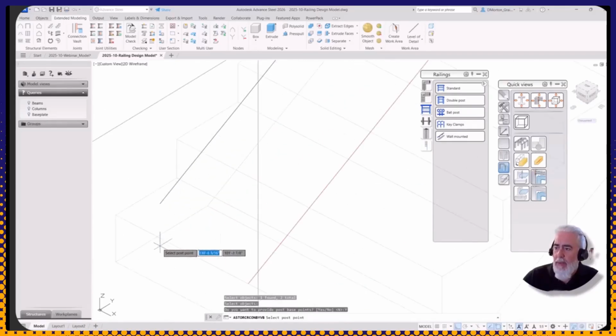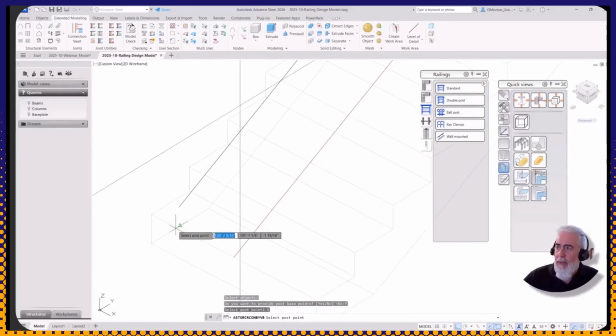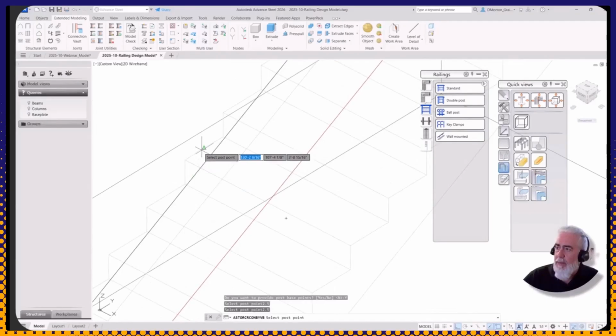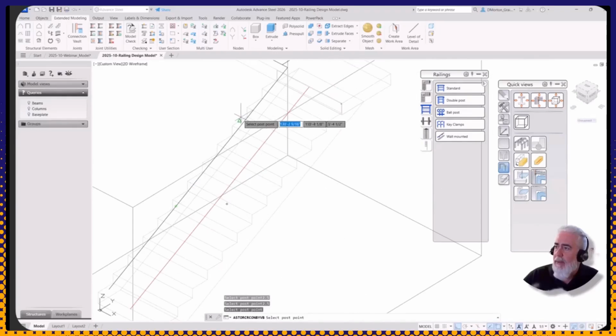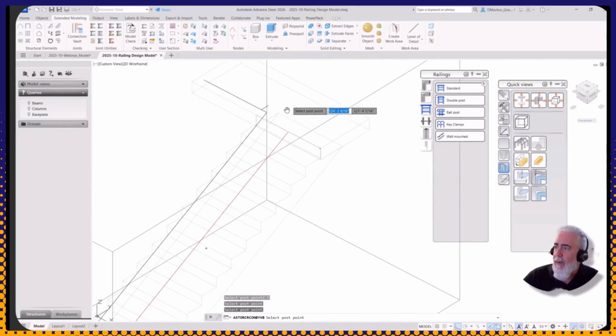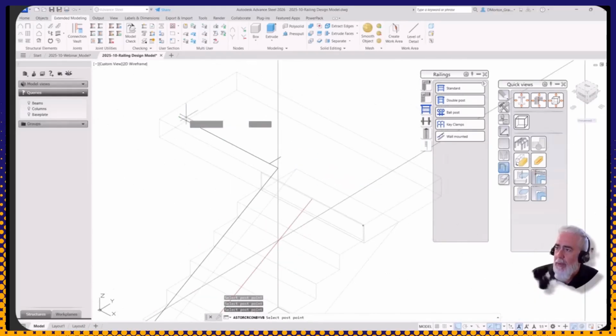And then I want to provide the post base points so they come out where I want them to show up. So here, I'm just going to come from the edge and I'll come in 2.5 inches. And I'll go up 3 stairs. I'll do the same thing again. Come in 2.5 inches. Come up there. Come in. You can see it's going to grab it there anyway. Grab that. Go up another one. There. And at the top, I'm just going to put it right around the corner there. I'll put another one at the end.